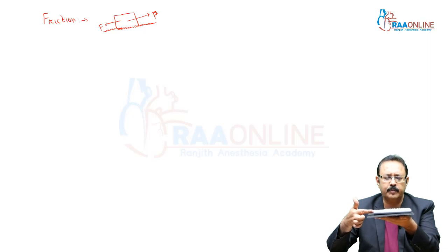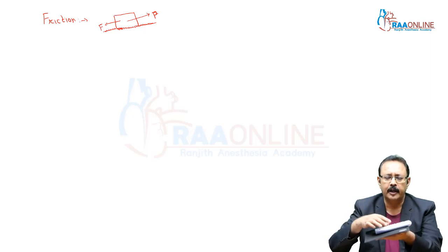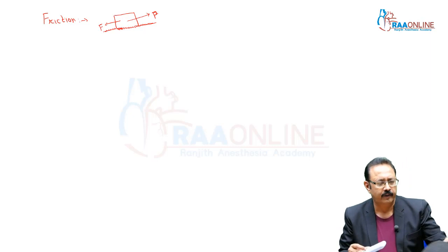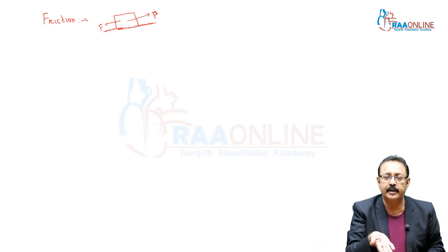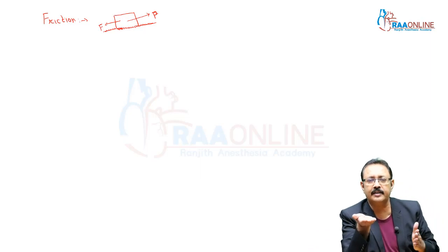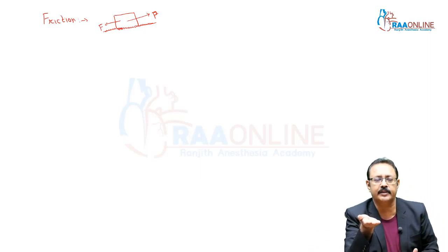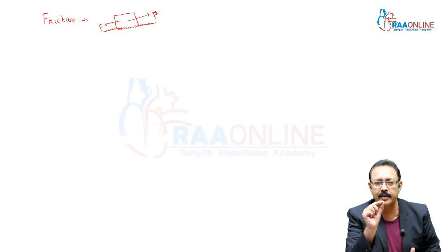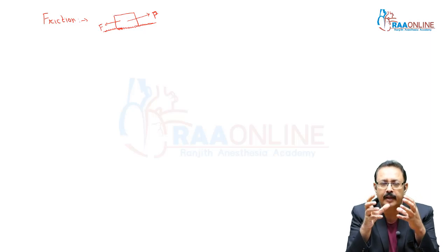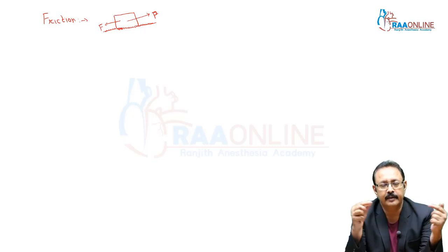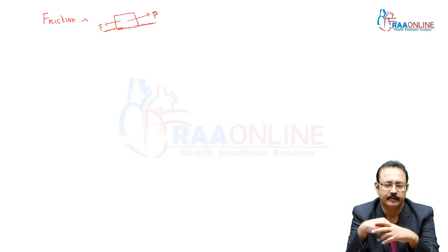But at 0.3, suppose it is moving. It means up to 0.3, the friction force was increasing its value by itself. But after a certain limit, it cannot increase its value, which is known as limiting friction. After that, if you apply a force bigger than that, then it will start moving. Getting my point?